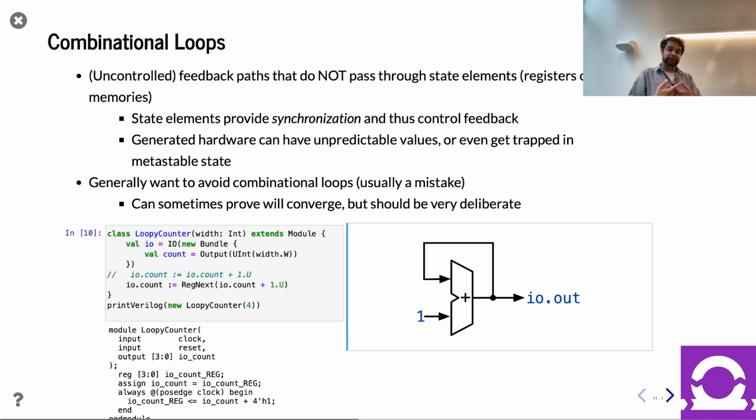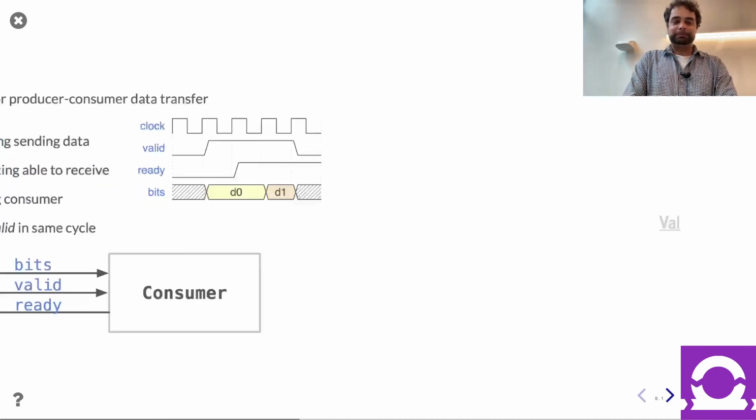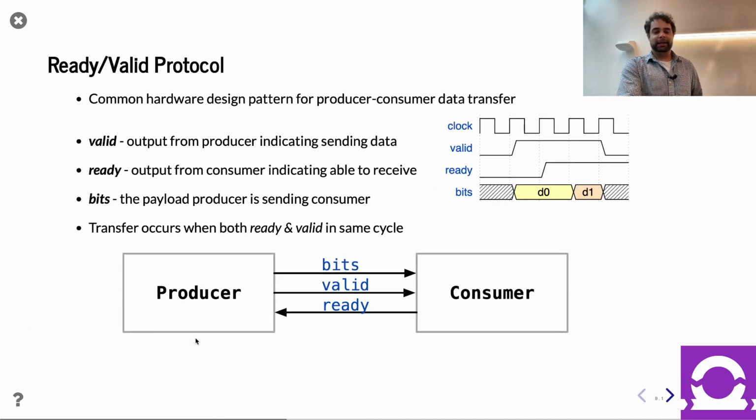And like I said, when it comes to ready-valid signaling, everybody's going to smile and nod today, and then in a week, when you do the homework, you're going to keep pulling your hair out. Like I said, just take a deep breath, look at your design, and realize that it may not be obvious. It may go through multiple modules. It may go through your state machine. But if there's a combinational path from here to here and from here to here, you're going to have a combinational loop. And so as long as you break up one of those, you're good.